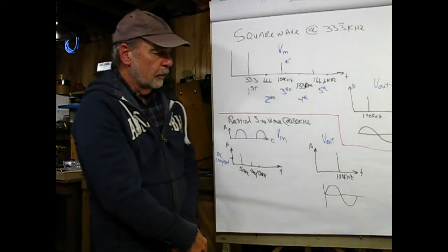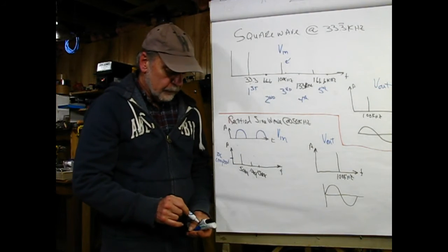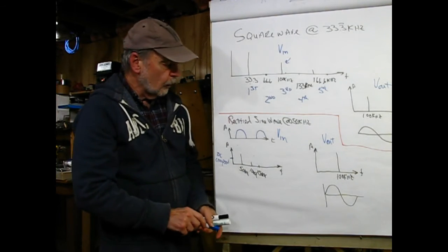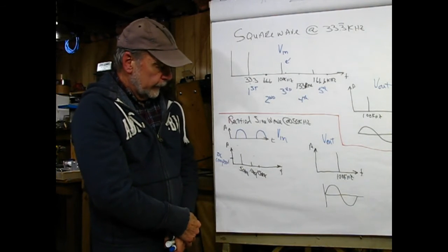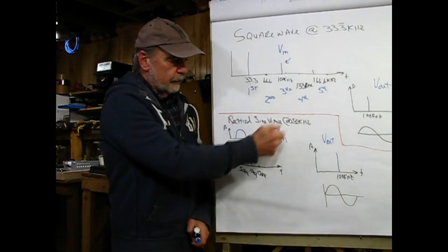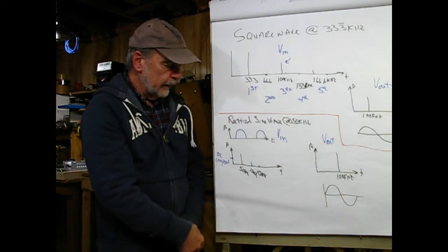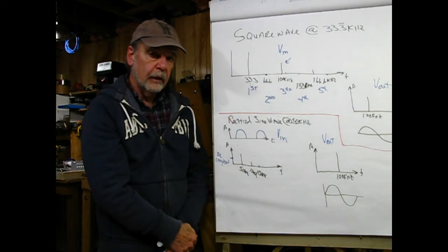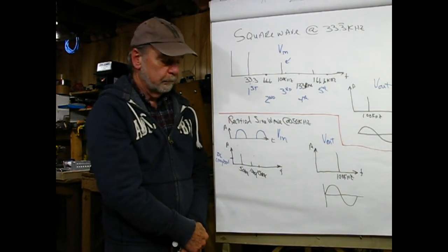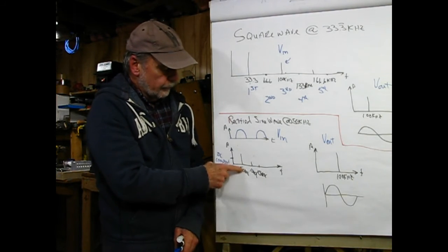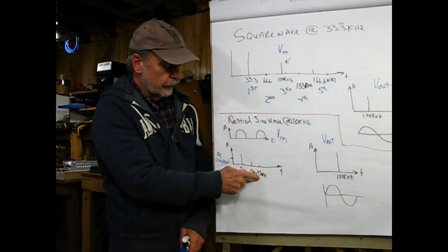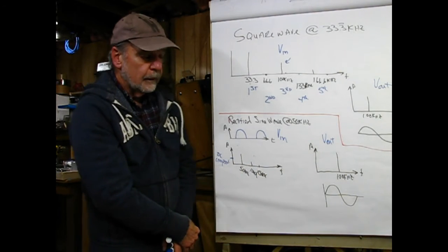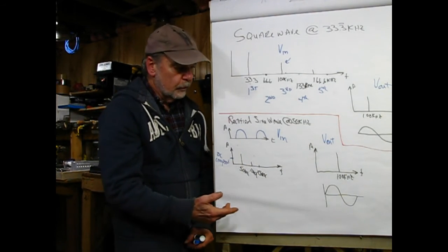So let's look at something a little bit different other than square waves, and we'll start out with a rectified sine wave. Kind of looks like this, and we'll let this frequency be 50 kilohertz for the heck of it. And with this particular signal, there aren't even order harmonics missing, so we get a fundamental component here at 50K, we have a harmonic here at 100K, another harmonic at 150K, and we feed this into our frequency multiplier.